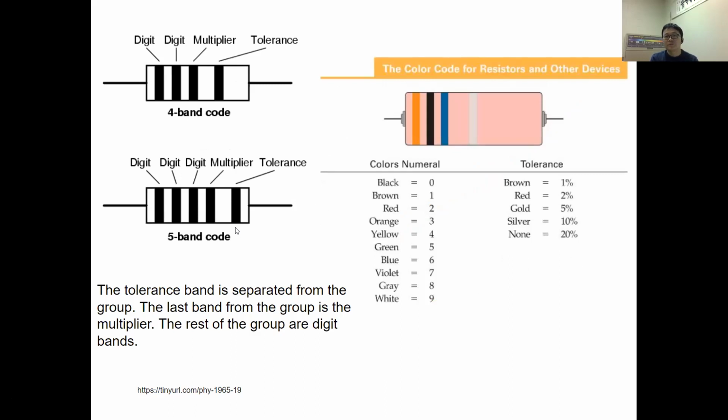So when you look at resistors, most often you'll find color codings. Some of them have 4 bands of colors, and some have 5 bands. We have done this in the lab. If you have 4 bands, 3 will be closer to each other, and 1 will be further away. And if you have 5 bands, the first 4 will be close to each other, and the last one will be further away from those.